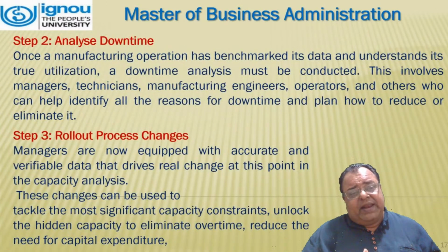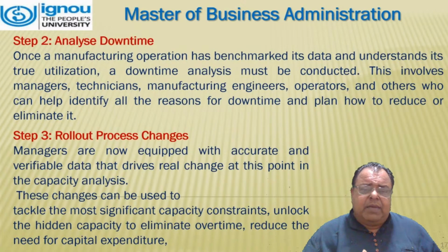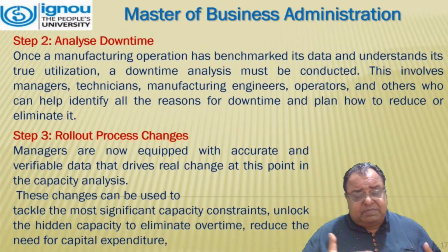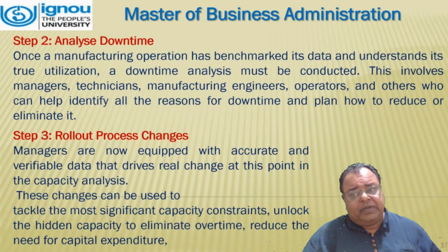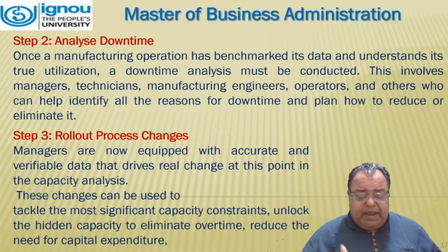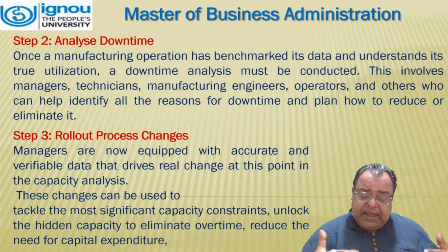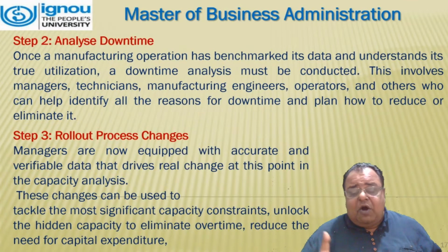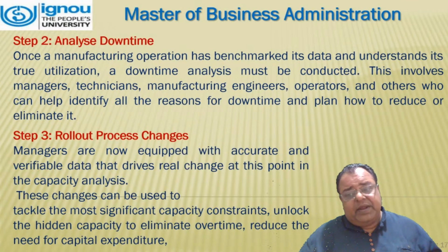Second step is to analyze downtime. Once a manufacturing operation has benchmarked its data and understands its true utilization, a downtime analysis must be conducted. This involves managers, technicians, manufacturing engineers, operators, and others who can help to identify all the reasons for downtime and plan how to reduce or eliminate it.